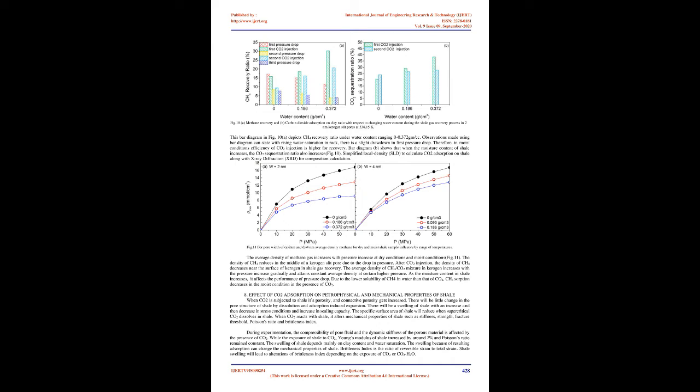Observation studies state that in a two-gas mixture injection of CO2 and N2, if the carbon dioxide percentage is much higher than N2, then a decreasing trend in the recovery of methane is the outcome. If the saturation of CO2 in the mixture is greater than 70%, then the sequestration and storage rate of the anthropogenic gas is quite low in the subsurface shale formation.